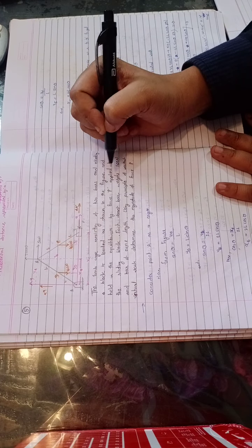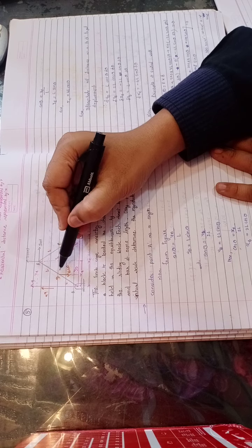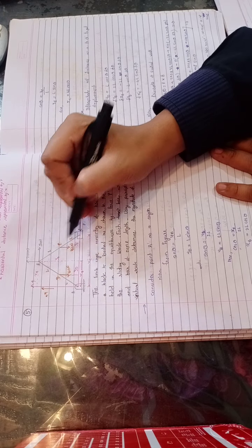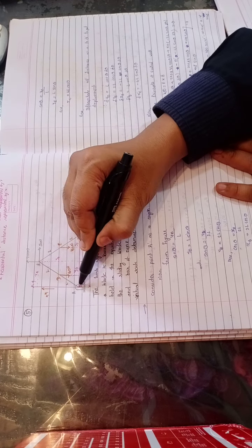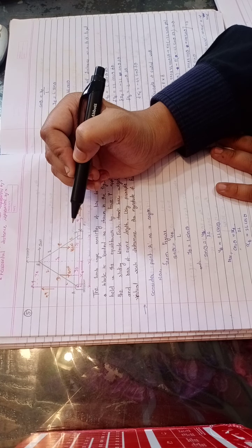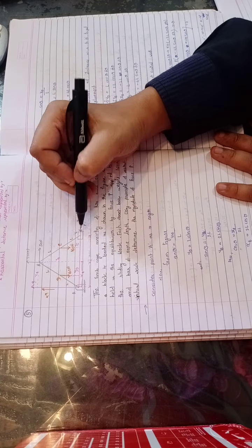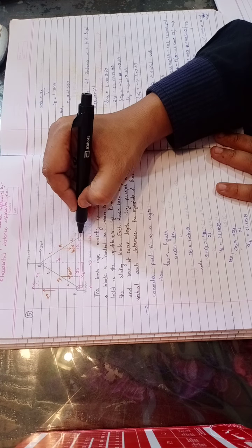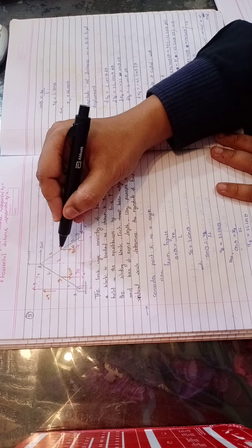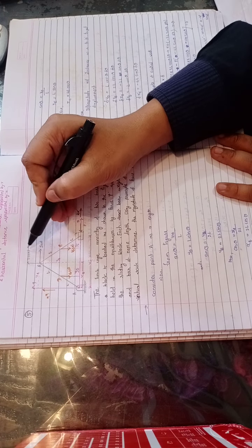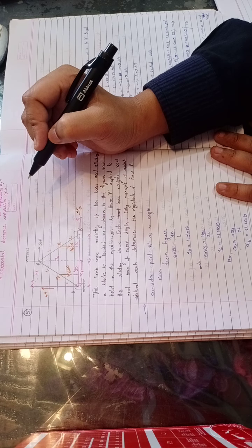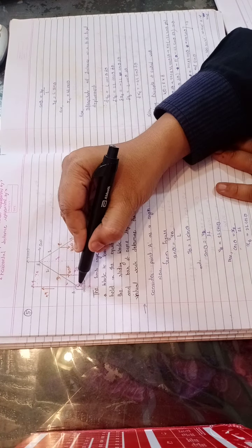Then the load 160 Newton of this bar will be acting at the center of the bar. So the total length of the bar is twice L, and this is twice L. So at a distance of L from A, 160 Newton load is applied vertically downward. In this case also the total length is twice L. So at a distance of L from point C, the load 160 Newton of this bar is acting downward. Again the load 250 Newtons is acting on the body, that is given in the problem. So consider A as the origin.